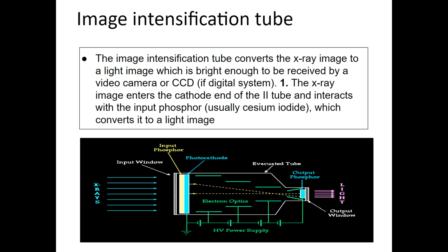You've heard this term before. And it will take an X-ray and turn it into wavelengths of light. Obviously, maybe I shouldn't say obviously, but the wavelengths of light are representative of the different absorption levels that the X-rays went through to begin with. So it's not just one wavelength of light, or else you get like one contrast. You don't want just a gray image or any one color. Right next to this thing, it doesn't even look like there's any space in between them. So sandwiched next to this is what's known as the photocathode,